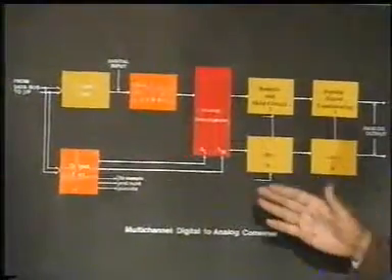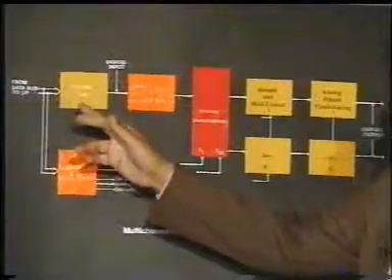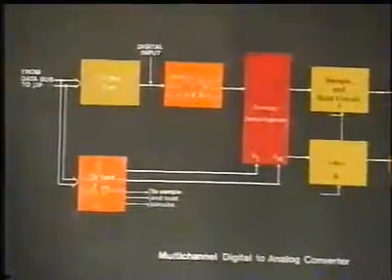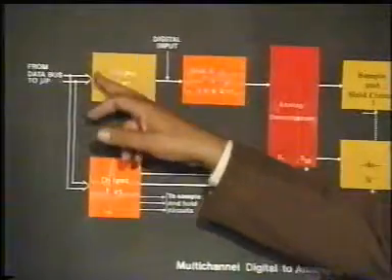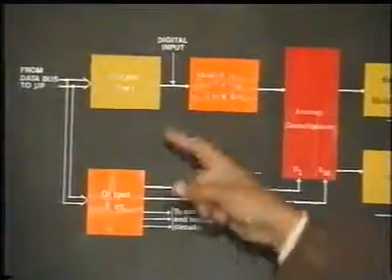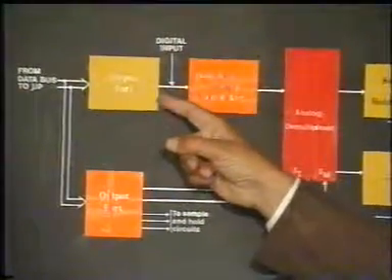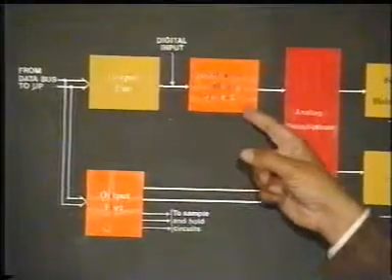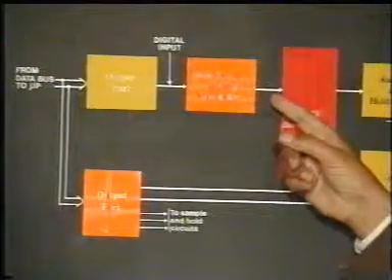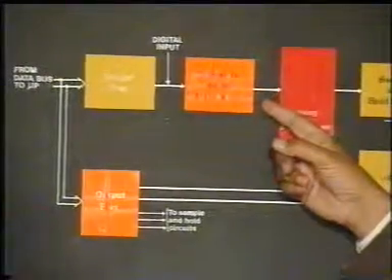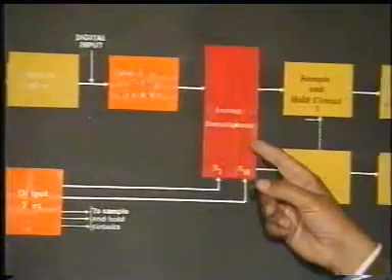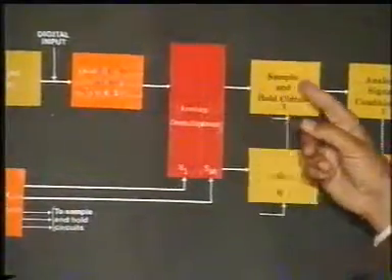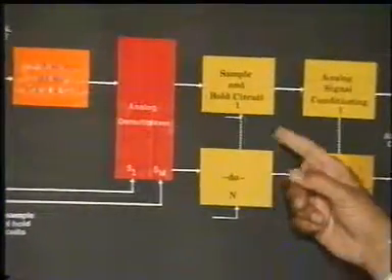Now if we similarly see, the digital output of the microprocessor can be directed to many devices. The digital output can be stored by the microprocessor into a port here, and then this digital output of this port is presented to this digital to analog converter, which produces an analog output here. Then through the analog demultiplexer, the analog sample can be directed into one of the channels to which it belongs.